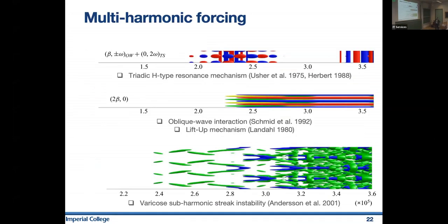And here I'm breaking down again the components for the forcing. You can see the forcing is a resonant interaction between oblique waves and TS planar waves that give vortices, streaks, and at high amplitudes, the streaks break down in a similar manner like the one we showed earlier.